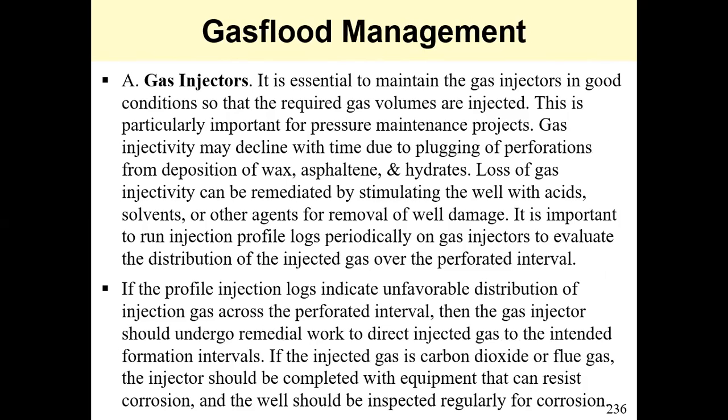So in managing gas floods, you also need to monitor your gas injectors, simply because injectivity may decline with time due to plugging of perforations from wax, asphaltene, hydrates, and of course, you might need to carry out some remedial actions to get back your injectivity.